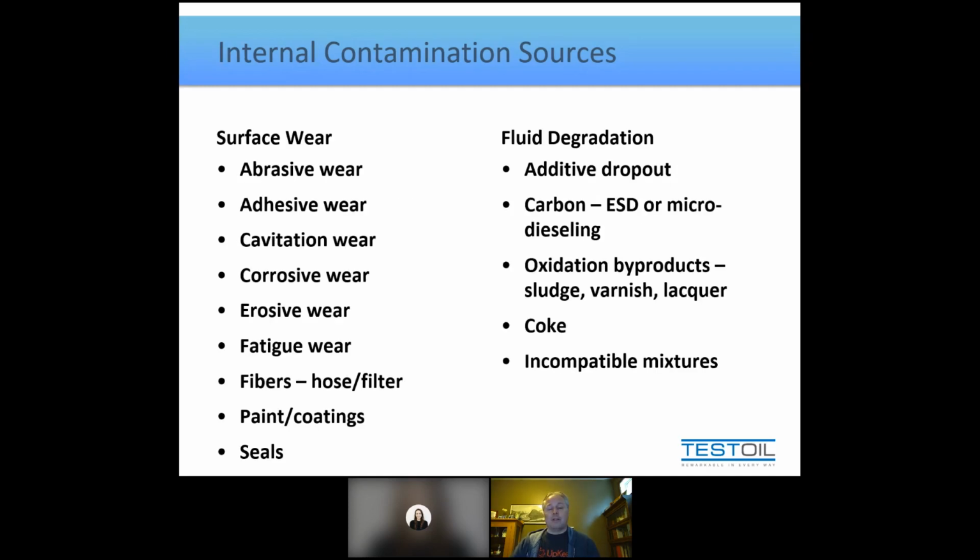On that last category of internal, I've given you a few examples here. Pretty much everything on the left-hand side are different physical wear mechanisms. But there are a couple at the bottom that are the very things that we install to try and minimize contamination or otherwise handle contamination that can actually contribute contaminants themselves to a lesser degree. So things like hoses, filters, and even seals, as they abrade or fail, they will release some particulate in the form of, generally, fibers and whatnot. On the right-hand side, though, is an interesting list of things that are created because the fluid degrades.